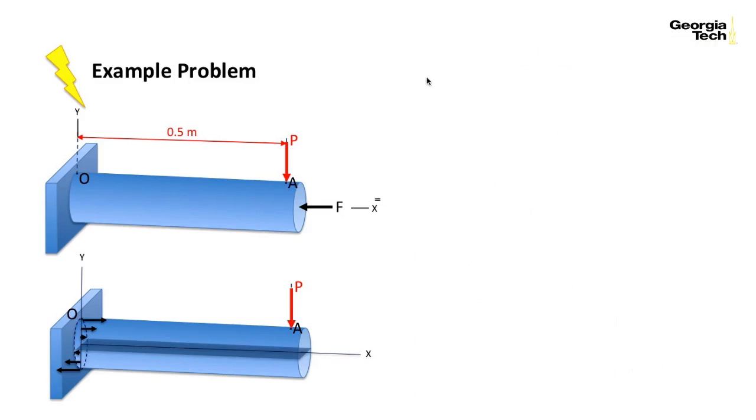Another thing to notice is that our bending stress, which is occurring, again, in the x direction, where you're stretching the beam filaments in the x direction, was right around 40 megapascals. And when we looked at our axial stress, also acting in the x direction, it was 0.8 megapascals. So even though the axial load was higher, the bending stress dominates, which is a really common thing. So it's always important to keep an eye on your bending stress because the values can get quite large.